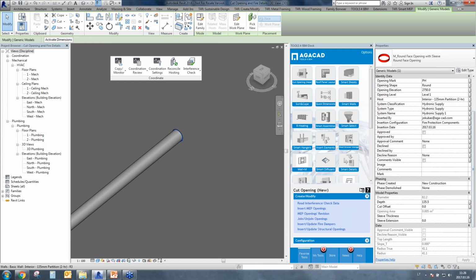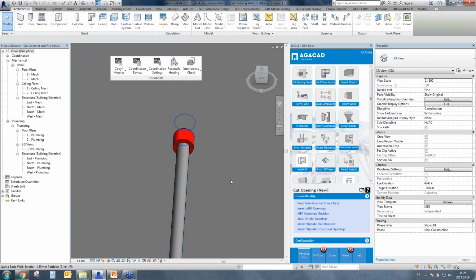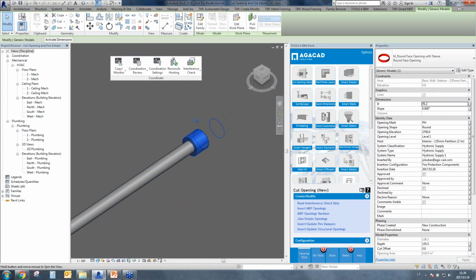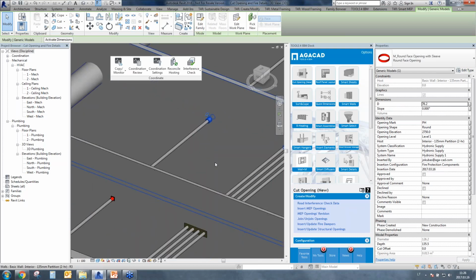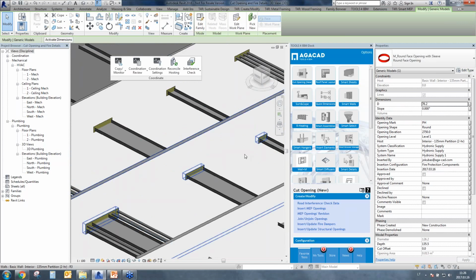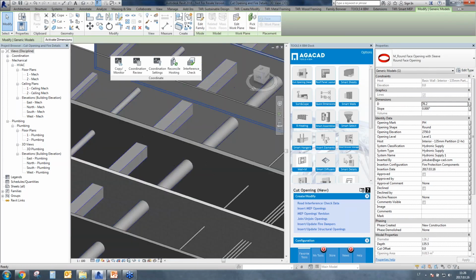Again, the fire sleeve is a little bit too thick, I think, so I'm adding special parameters that look like this. So extension from the wall, the thickness, etc. So everything is manageable from the families, or from the project, or straight from the cut opening software. So this is how you can distribute details inside.